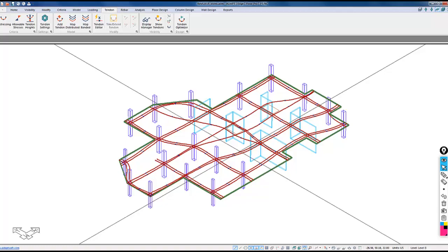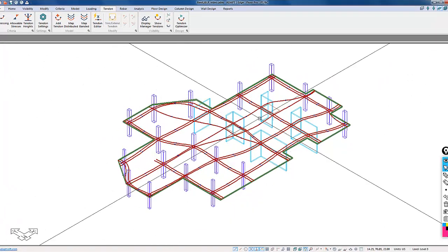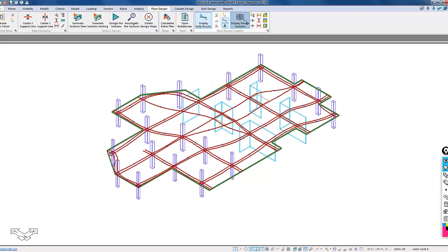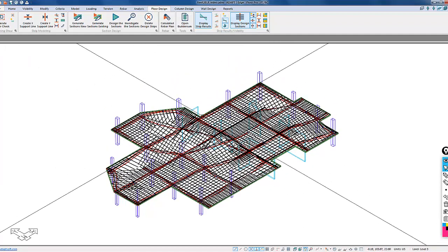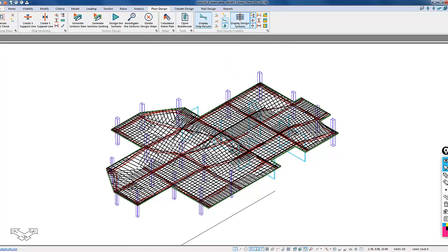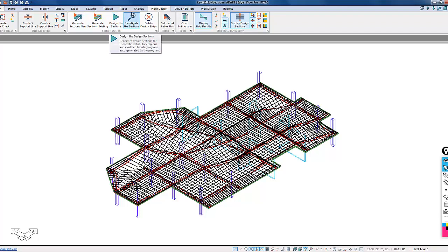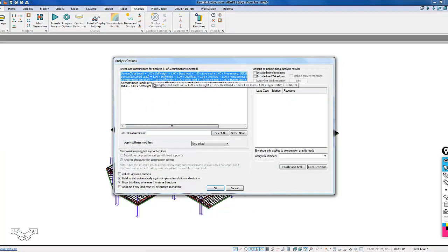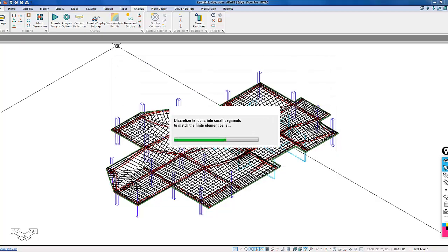So we now have the tendons worked out in both the X and the Y directions. We also have the design strips for the floor. If we go to floor design and I turn on the strips, we have the design strips here. So we're going to go ahead and just design this floor, assuming these tendons and the force in the tendons, and we'll go ahead to analysis. I've already meshed the model, so I'll go ahead and just execute the analysis and obtain some reinforcement.